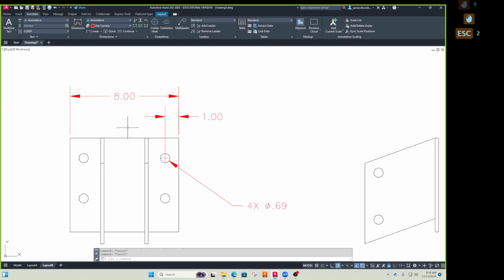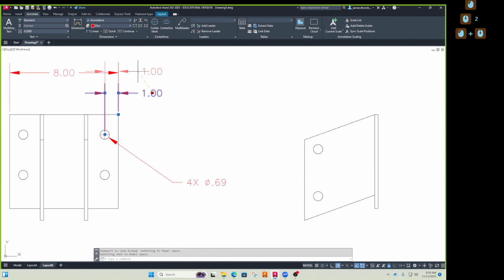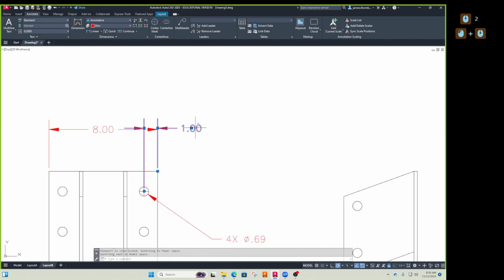Yeah. So when we're dimensioning, remember, I'll put my checklist for dimensioning rules here. One of the rules is that we have the extension lines come from the part up, and we have the dimension line that has the text and the arrows and stuff. You can't cross the dimension line.